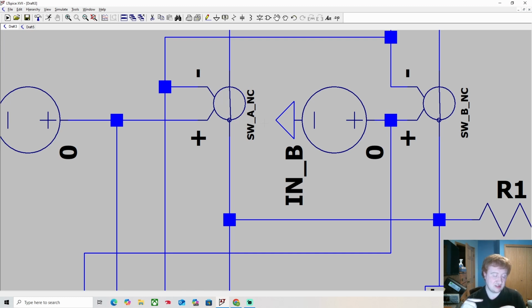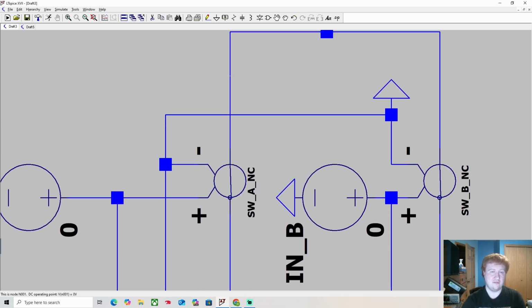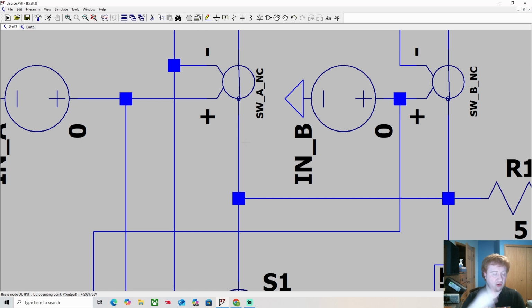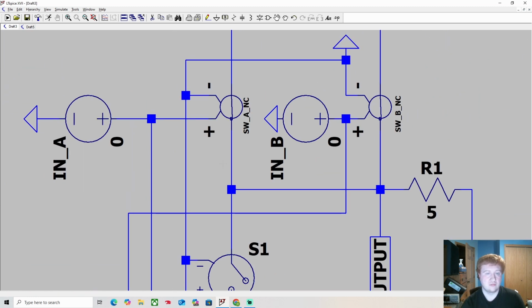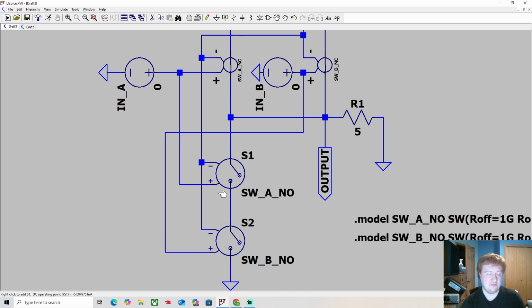And as soon as you press that button, there's a little piece of metal that travels away from the circuit so that it interrupts the path between one side of the circuit and the other, so no current would flow through the path. So it's like a default on kind of thing, therefore normally closed. And of course, normally open means that if the button's not pressed, there's not going to be any current flow through that path because it's open.